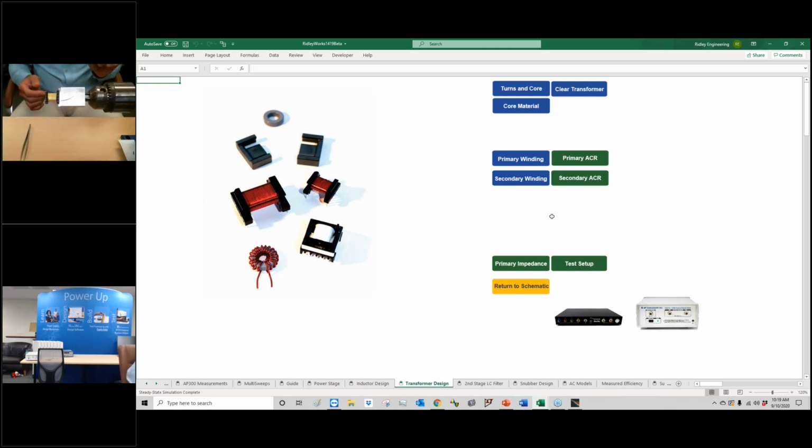Spin it around and show you. There you go. Wasn't too bad. All right, secondary. Now I've got 2 wires. This is a good idea when you're producing your magnetics, to use 2 different colors. I've got a red and a green here. So when you put them down, you can see whether they've crisscrossed, and it's easier to count the turns afterwards. If you don't have a winding machine, that's especially important.